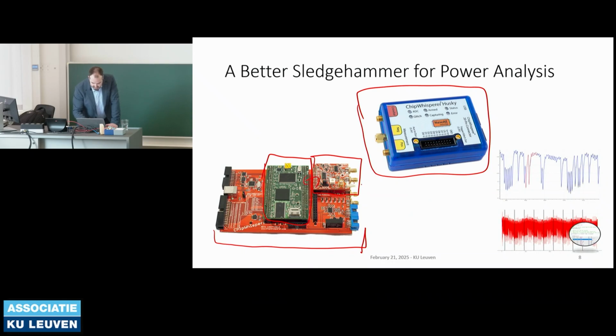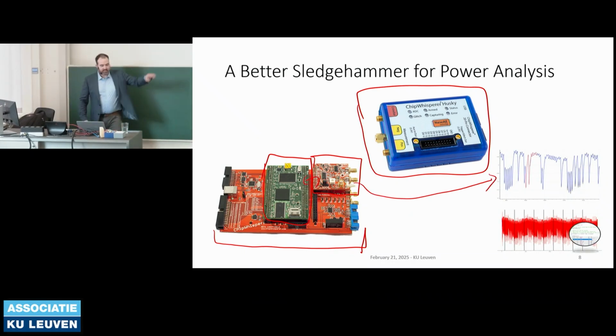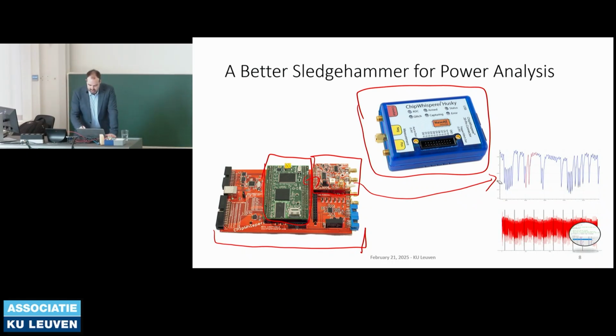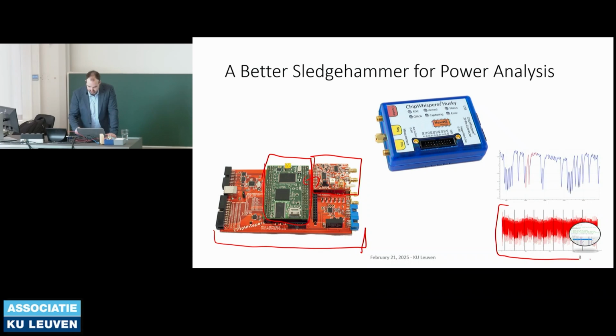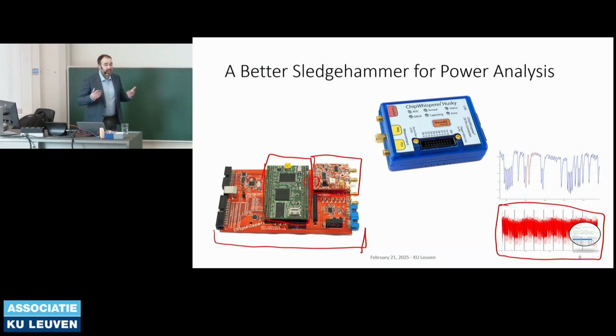These are what's giving us our nice power traces here. The same sort of stuff is in this later design. This later design also adds things like you can trace on ARM debug. So with ARM ETM, there's this debug capture format, so you can figure out what your power trace is doing and correlate it with instructions being decoded. So it's really useful for developing algorithms and testing them.